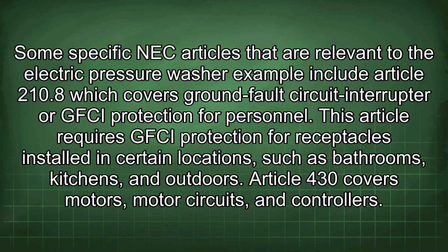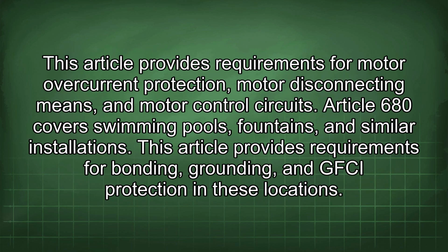Article 430 covers motors, motor circuits, and controllers. This article provides requirements for motor overcurrent protection, motor disconnecting means, and motor control circuits. Article 680 covers swimming pools, fountains, and similar installations. This article provides requirements for bonding, grounding, and GFCI protection in these locations.